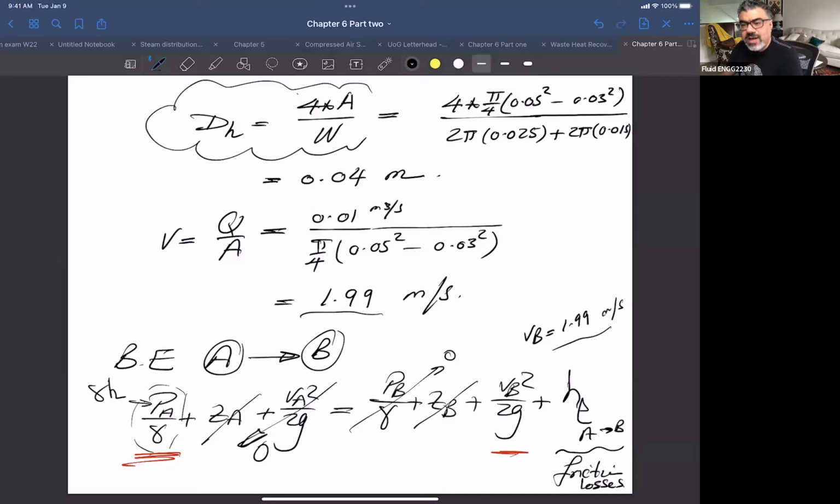So we are converting a non-circular duct to a circular duct, and then the rest of the problem becomes the same. We treat this as if it's a normal pipe with a diameter. So we calculate the Reynolds number the same way, and the friction factor based on epsilon over D, but all the diameters here will be hydraulic diameters.